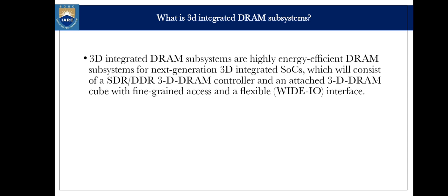What is a 3D integrated DRAM subsystem? 3D integrated DRAM subsystems are highly energy efficient DRAM subsystems for next generation 3D integrated SoCs, which will consist of SDR or DDR 3D DRAM controller and an attached 3D DRAM cube with fine grain access and flexible wide I/O interface.